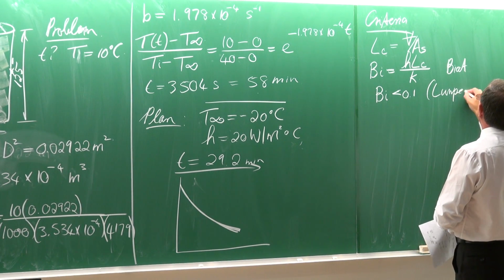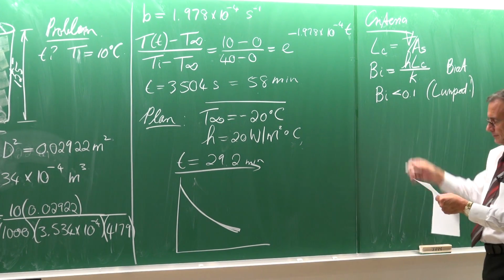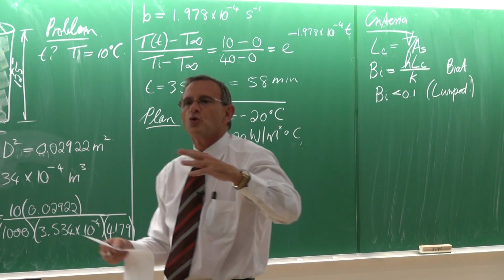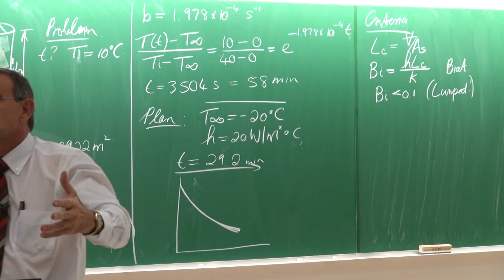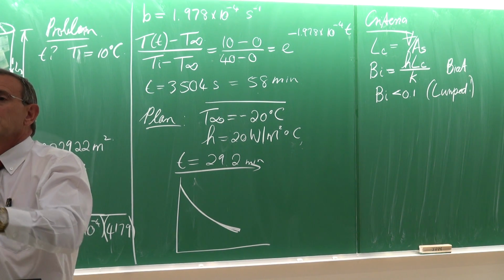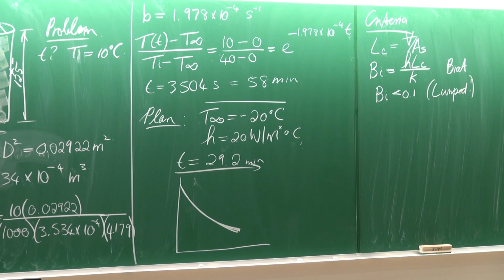So you can go and test with a Biot number to determine if you can use this approach or not. Okay. Now, the thing is, that is all good and well, but the question is why? And that is why you as students also should ask yourself always, why? Okay. So why do you think must the Biot number be smaller than 0.1 and not smaller than 1?